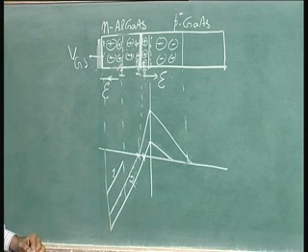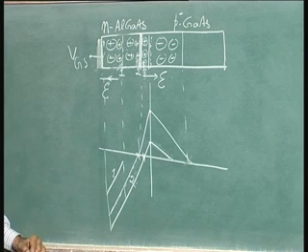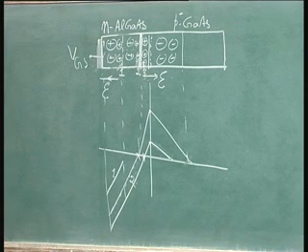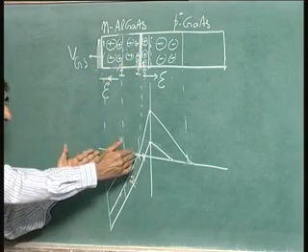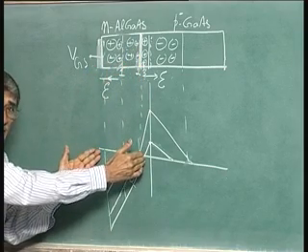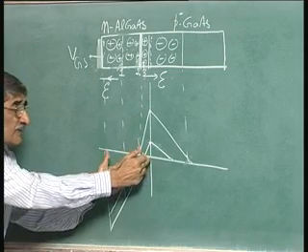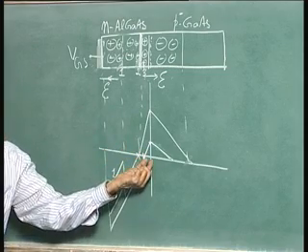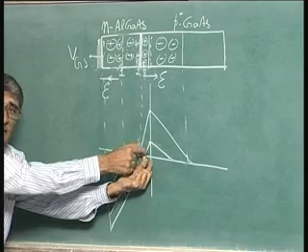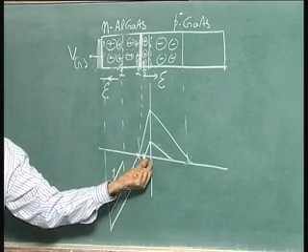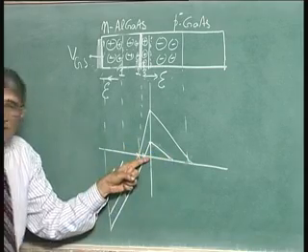Okay, what has happened now, physically, is that we have argued it out by pushing the depletion layer towards that side, so that the depletion layer belonging to the Schottky barrier has widened, and the depletion layer on this side belonging to the p-n junction has reduced because of that. If it has reduced on this side, the charge on the depletion layer of the p-n junction has got reduced, plus charge. That means the minus charge on this side has got reduced.